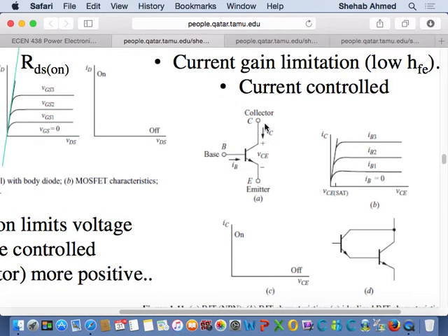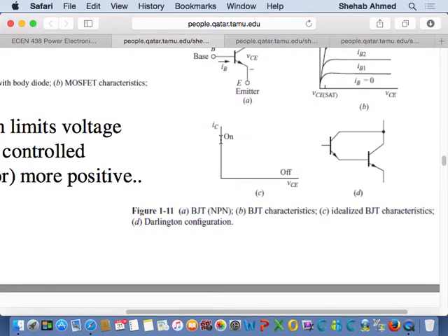It's the collector current multiplied by the VCE voltage, collector to emitter voltage. And the collector to emitter voltage is a junction voltage, like the diode junction voltage, right? And you will extract it from the device's data sheet, or we will give it to you in the problem. Okay? But they have losses. In reality, they have losses. It's not pure 0 volts across the device when the device is on.